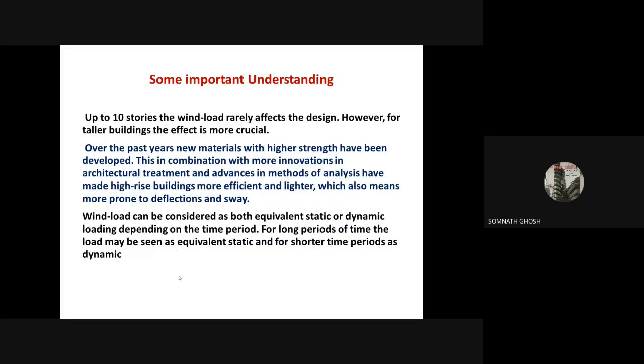Now you see, for a 10-story building, suppose in Kolkata, you may not face any wind problem. You will find that for the 10-story building in Kolkata, maybe the dead load plus seismic load combination is critical. But we are not talking about 10 stories. We are talking about 100 stories, 200 stories.